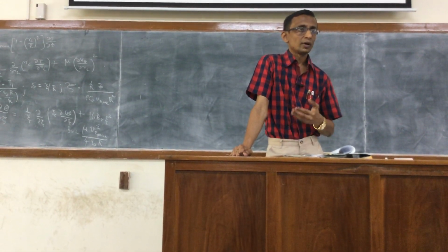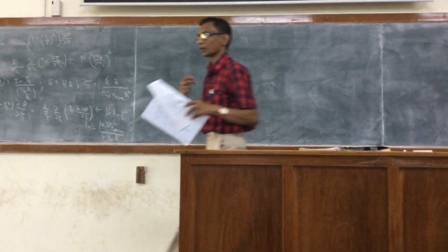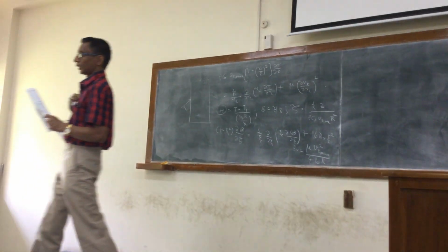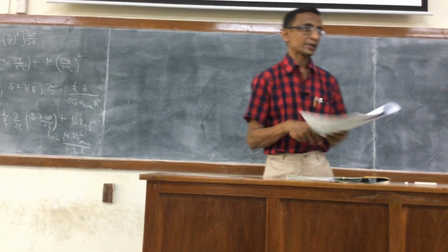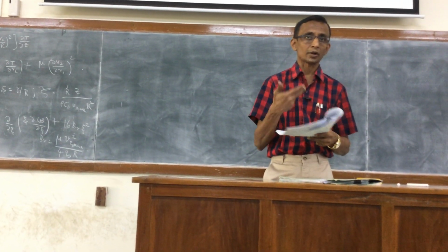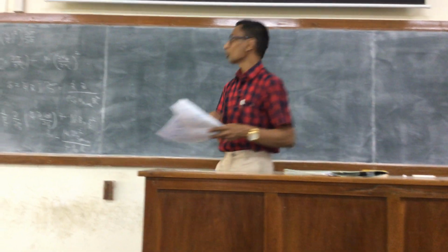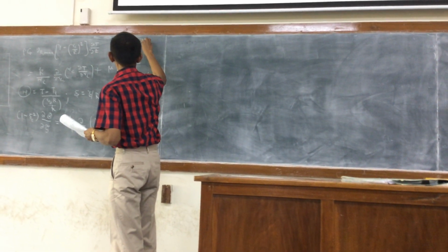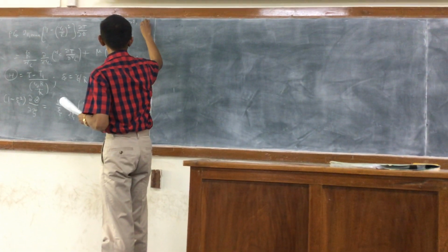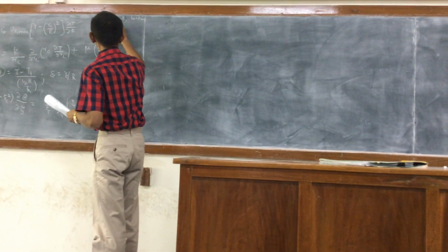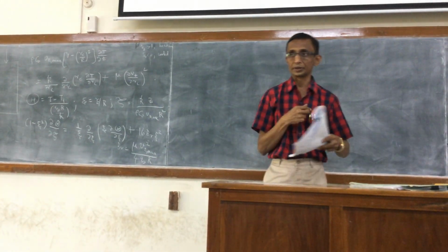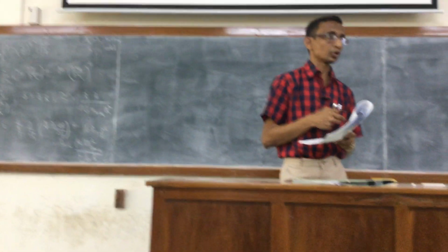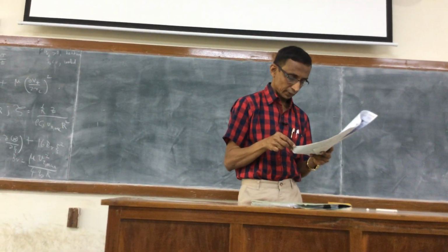The ratio of that, right, can be regarded as a measure, the ratio of the viscous, the energy transfer or the energy generation, viscous dissipation to the external heat transfer or flux that is provided in order to heat or cool the fluid. So Q naught greater than 0 would mean that the fluid is being heated. Q naught less than 0 means the fluid is actually being cooled, or its temperature is reduced as it flows down the tube, depending on the purpose that is required.